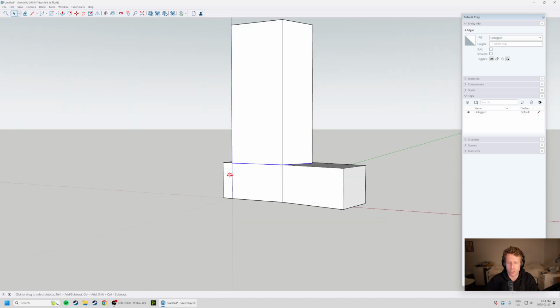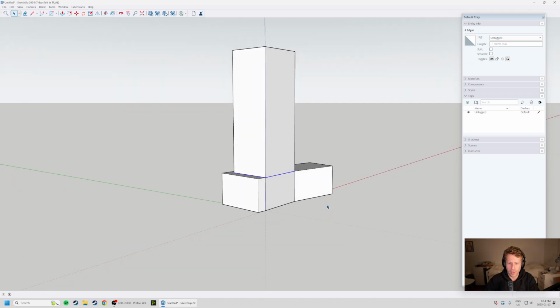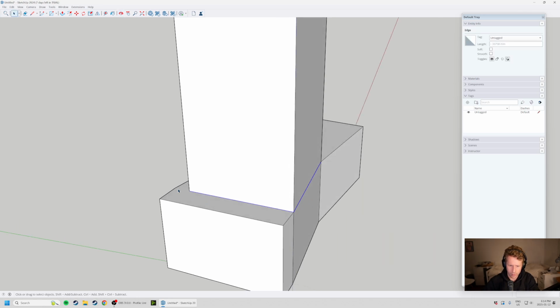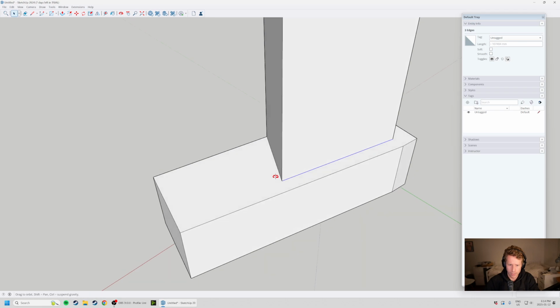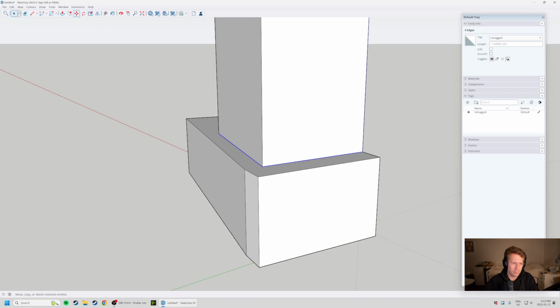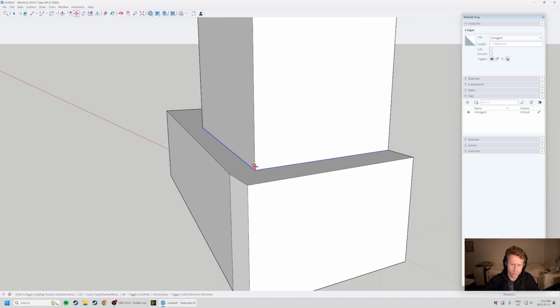It's really hard for us to imagine, based on this shape, what 3 meters per floor looks like. So sometimes in a model, you might want to show every single floor. In this case, we're going to say it's about 3 meters of floor plate per floor. So right now I've got those 1, 2, 3, 4 sides of that piece selected. I'm going to click once, Control-click again, Control-click a fourth time. Then I hit the Move button here, hit Control, and I can come up by 3 meters, hit Enter.